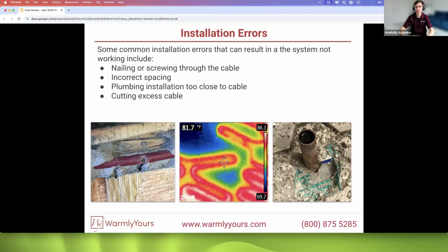We can see literally a position of the wire under that tile. And in this case, again, we only can speculate something happened and that heating system or section of it was not installed per plan, and some section is not covered at all. There is a triangular section that doesn't have a heating element.